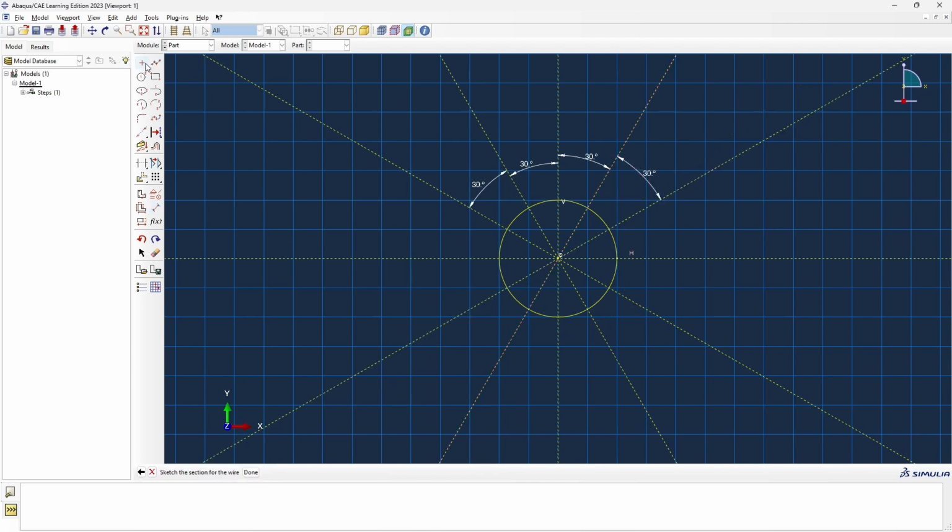Now once that's done, hop onto the mini toolbar again. Now choose the second column first row option called create lines. Create the hexagon. Now it is important that we're doing a hexagon that is in the zigzag orientation instead of armchair orientation. So once that's created, press escape to end the operation.